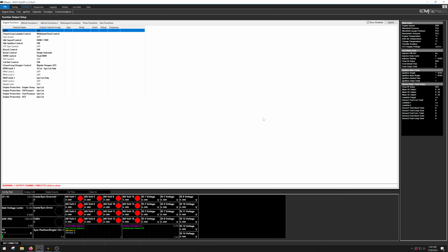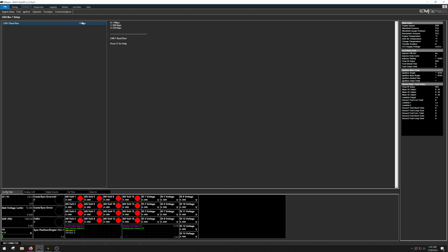for your usage. So I have my PMU file for the front opened up here, and I have the ECU one in front of me, which I know I need to fix. Don't worry, it's good that it does notify me though. So if I were to go to communications, you're going to have a CANBus set up as a rate. You're going to have CANBus through channels and the predefined data sets turned on, right? And then you have the rate at which it's transmitting, how quickly it's transmitting.